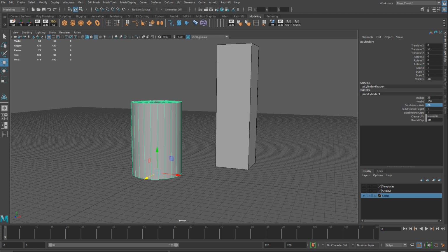Since I want this prop maybe duplicated dozens of times, maybe hundreds of times, and reused over and over again, I'm setting the stage ahead of time for what my ultimate goal is going to be. I'm just picking a number I feel comfortable with for this prop, because I know it's going to go into UV4. I know the triangle limit is becoming more and more irrelevant, but it's still good to have some sort of a base to start with. It really helps you decide how much detail you include and how much you have to leave out.